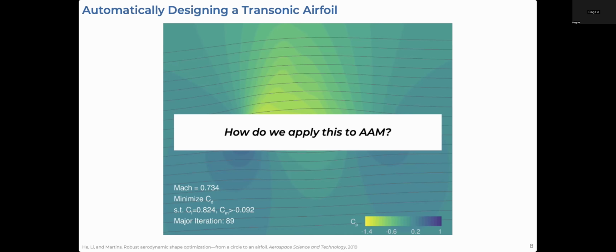We run a low fidelity propeller analysis to understand the blade load distribution from the propeller and impart it on the wing. So we compute propeller blade loads, and we put them on an actuator zone that is steady state inside of a DAFoam simulation. We parameterize this with design variables, and we get function outputs. And because DAFoam and the other tools are gradient based, we can get the derivative of the functions with respect to the design variables to perform gradient based design optimization.